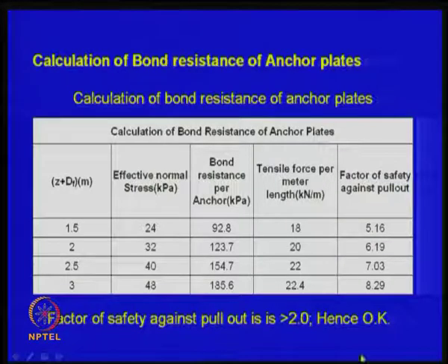And now you see that the factors of safety are more than required, and the fact is that now it is B equal to 3 only, not as when B is 1.5 meters. It is okay. If you want, you can even reduce it; there are different ways. See, now you got the bearing resistance as an important contribution.